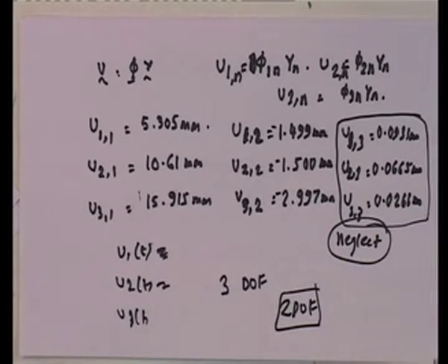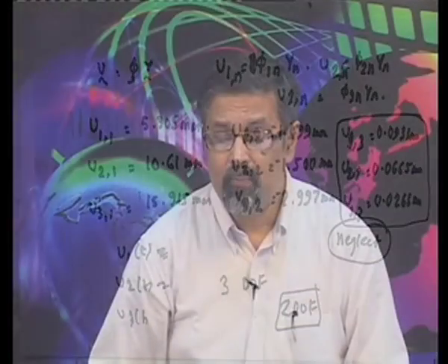Okay. Now, this is a very peculiar situation where it is a harmonic load, and where the largest displacement is really in the second mode. Okay. That is a very interesting point to note, because the largest dynamic amplification that you have in this particular case is actually in the second mode. So, despite the second mode being actually dynamically more excited, because 1.5 omega 1 and omega 2 upon omega 1 is about 2, right. So, it actually comes very close to the second mode.